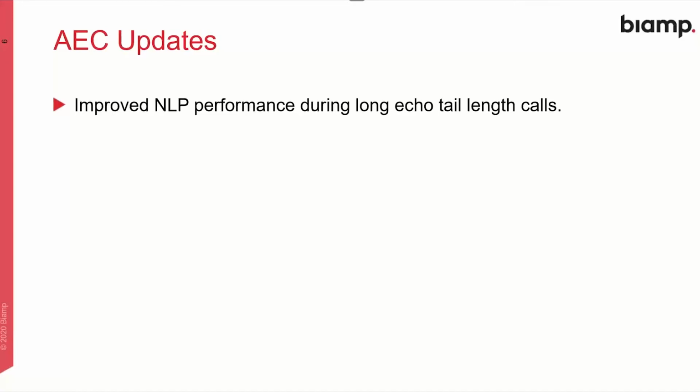The way that works, AEC, acoustic echo cancellation processing within Tesira, is a given tail length window. And once that tail length is processed, if you have any echoes that show up outside of that tail length window, then NLP is what I call the cleanup guy, or the cleanup algorithm that handles that if the AEC missed it or it was outside of the tail length. So NLP has been improved for those long echo tail length calls.